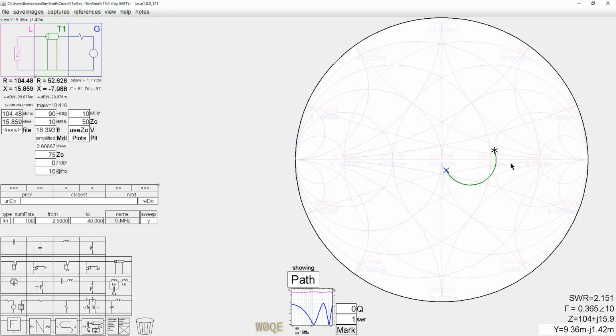So things like a one wavelength quad loop, rectangular, square, triangular type delta loops all have impedances in this range, which is why this quarter wave section is used. If I used the standard quarter wave section I did before, I'd end up being here. Oh, actually, before I go too far here, I should mention one other thing.